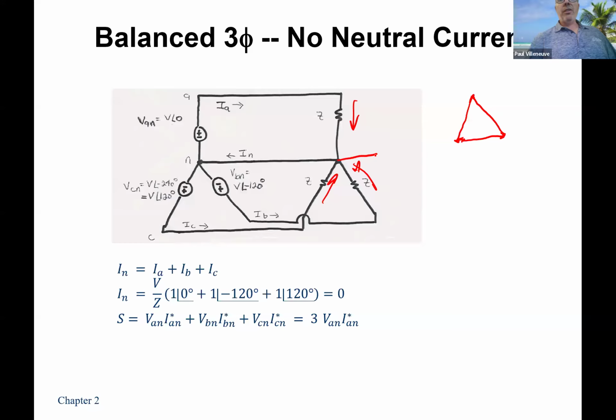And most neutral systems are connected to ground. And because there's no current in there, most of the time in a balanced system, why would I run that conductor? It costs me money. So most three-phase systems, you don't even run a neutral to it because it's not being used for anything. There isn't even a place to connect it. So almost all your balanced three-phase systems, you don't run the neutral. You still have to run a ground conductor, but you don't have to run a neutral conductor.